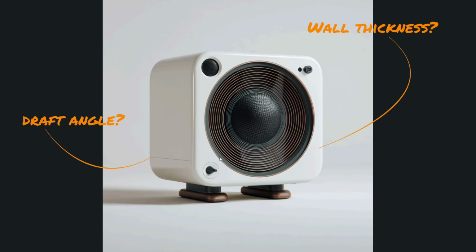Very simple geometry again, right? You would think that it's easy to make this, and it potentially is quite easy to make, but it will change things. Like if this is the parting line, then we have the mold that goes to the bottom and one that goes to the top. And then we have a much stronger differentiation between the direction of the bottom part and the top part. And then we really lose the organic cubic shape here.